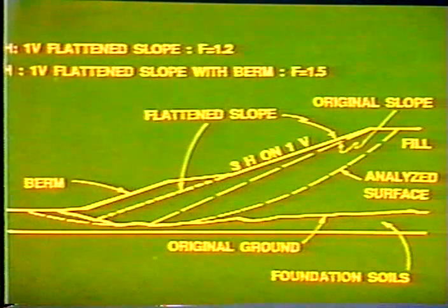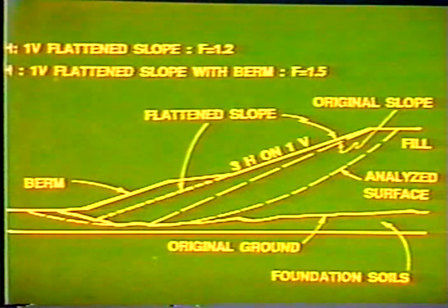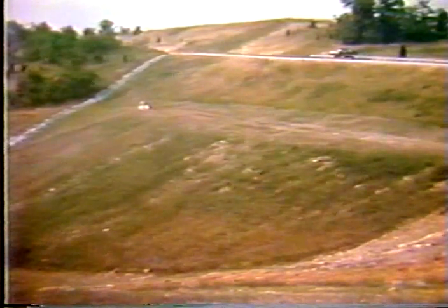The emphasis here is not the numbers necessarily. That's what a geotechnical engineer looks at. But for a maintenance person, what I want to point out is that you increase the stability tremendously when you build the berm with the flattened slope. So those are two good combinations. Just an example of use of a